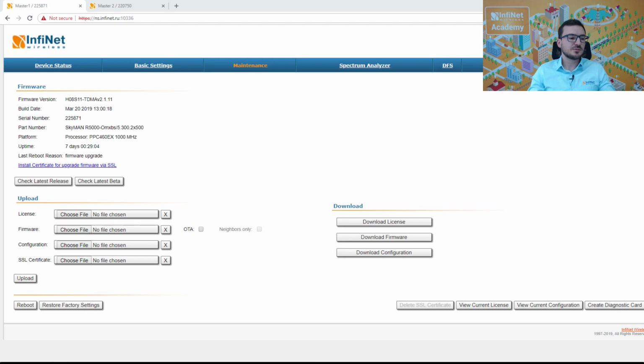Right, next question. What can you do when you have too much signal, like a received signal level of -10 dBm due to a very short range, so a very short link? First of all, you need to check that you have the lowest possible output power. Then maybe choose some lower gain antennas, and in some extreme situations it might be a good idea to use external antennas and use some RF attenuators between the unit itself and the external antenna.